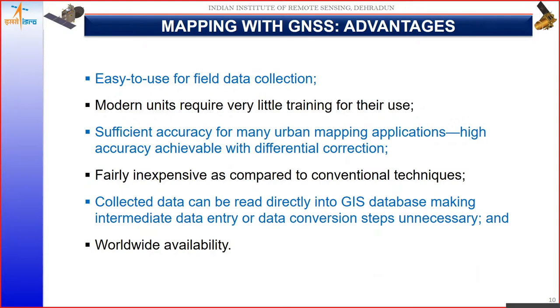Think about 100 square kilometers, and when you want to do georeferencing with classical surveying methods and acquire the GCPs, think about how much time it will take. That is why GNSS receivers help us a lot: in limited time you can acquire the GCPs and then do the correction.